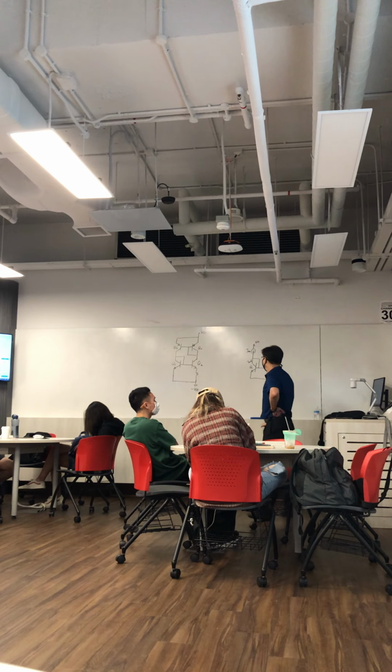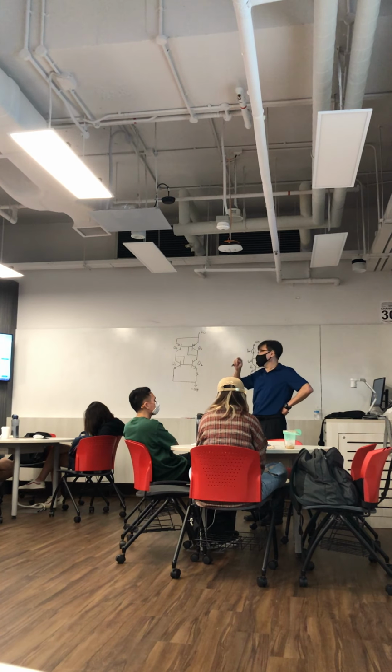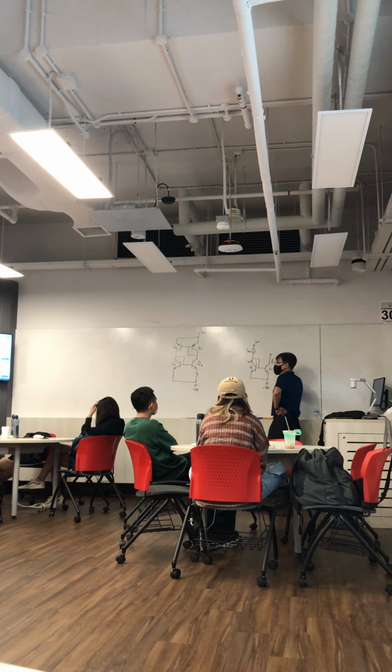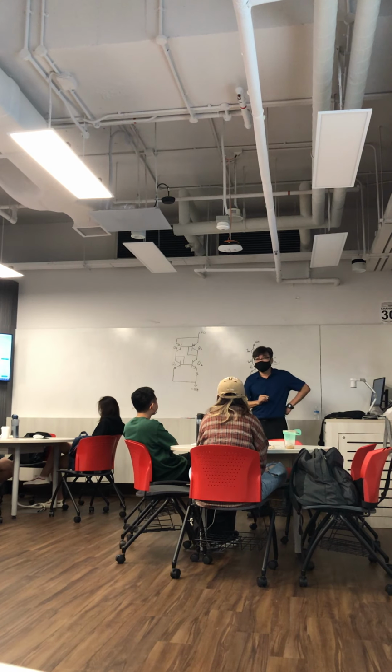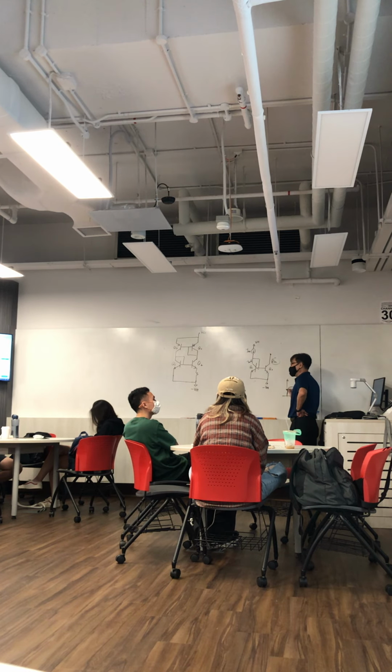source, this point, the voltage I put anywhere doesn't matter, okay? Because the current will be relatively constant given by this. So far so good. Because this guy, I already unconditionally biased in the forward active region. Theoretically, depending on the VBE here, 0.7, 0.6 or whatever, I have a curve here and I'm biasing somewhere here. So then it's determined by this guy.